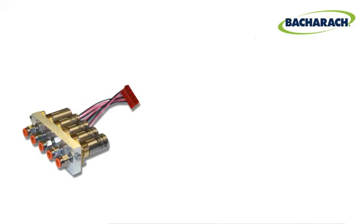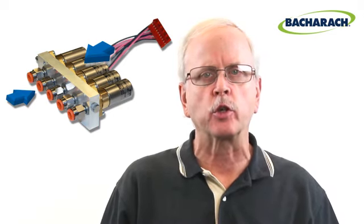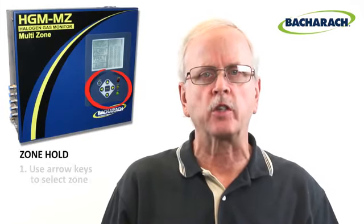At this stage of troubleshooting, the no-flow zone fault is likely to be caused by either a mechanical problem with one or more solenoids in the manifold or an electrical problem with the printed circuit board that controls the solenoids. To determine which, we'll first confirm that the suspect solenoid in the manifold is actually energizing. You see, if we can isolate a suspect zone and then somehow verify that the solenoid is indeed being energized, then we can assume that the solenoid control board is doing its job and the problem is a mechanical solenoid issue within the manifold. To do this, we must first put the suspect zone into a zone hold state.